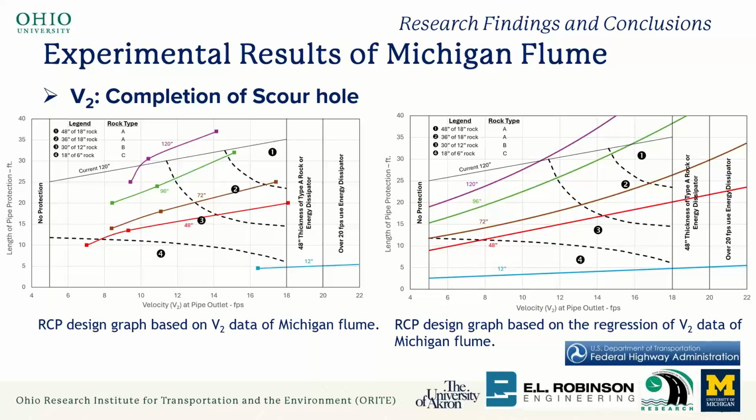But regardless of whether the outlet at the culvert is supercritical or subcritical, what this implies to us is that once the flow is out of the culvert outlet and it's affecting the stone carpet and the sand bed, it's already subcritical.